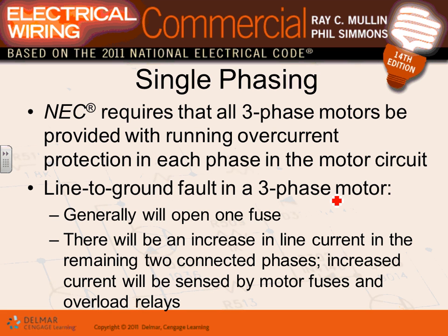Okay, single phasing. Three-phase motors must be provided with running overcurrent protection devices. For single phasing, if you have a motor and you lose one phase, the motor will continue to run. It was running on 3 phases, I lost one phase, and now it will continue to run, except these 2 phases will pull more current to compensate for the loss of that phase. What does that mean? You're going to burn them. But we have an overload protection that typically trips. And if the overload protection does not trip, the fuse will trip, if it's sized properly.